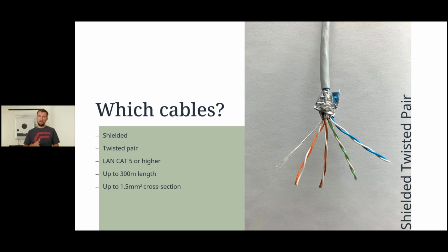And that brings us on to the next part, the twisted pairs. Most of our communication cables are always going to consist of 4 twisted pairs. Those 4 twisted pairs comprise 8 wires in total, always a colored wire and a corresponding white that is twisted with it. That'll be important when we come to the schematics. You saw beforehand that we had a colored line, in that case an orange line, and a dotted or interrupted orange line. That would be a fully blocked color, the orange wire, and its corresponding white is then the white and orange.